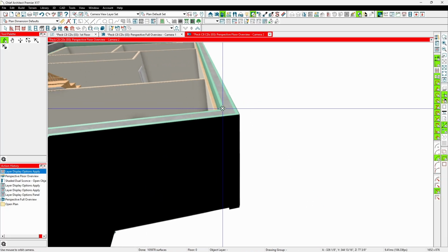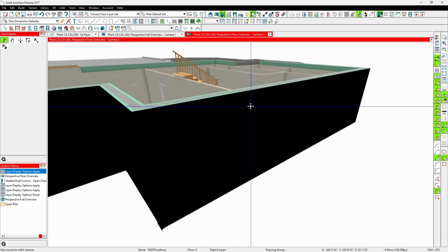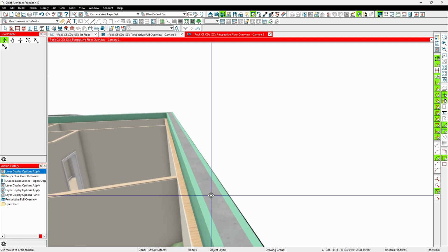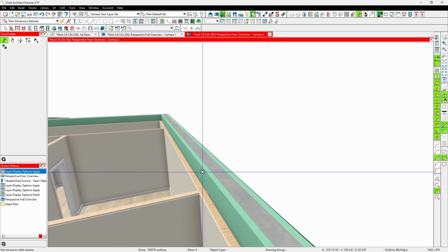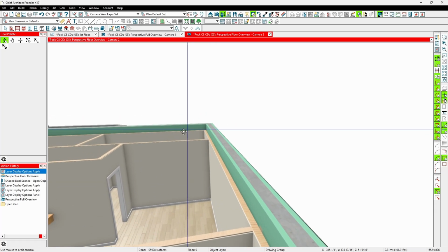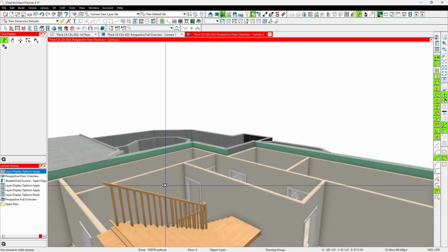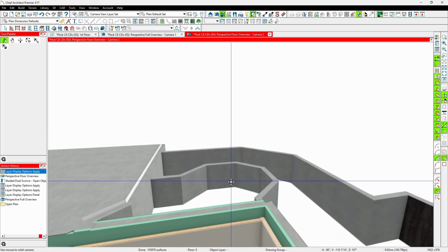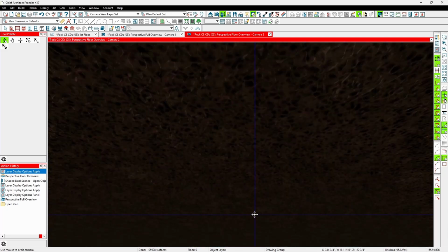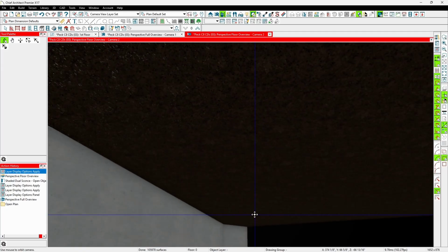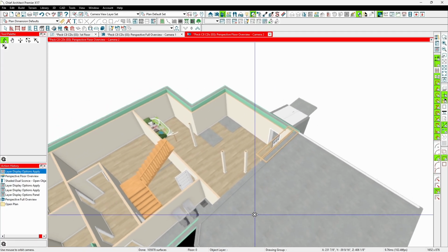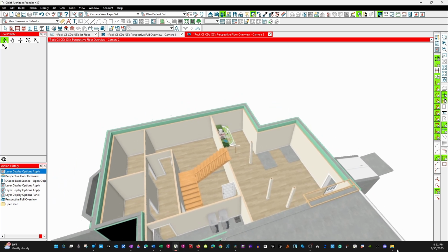And I can explain things like, here's our waterproof barrier on the outside. In this case, we're using a Nudura ICF, which is insulated concrete form. And then we have a furred-in wall, so we can do all the electrical and stuff on the walls inside the basement. Over here, this is all crawl space. And then this is the garage, which is, of course, just dirt underneath it. But it's a good way to get a view of how the house looks.